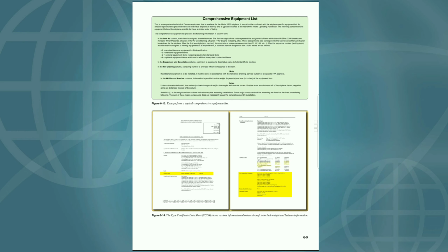VFE, flaps extended, 125 mph, 109 knots. VLO, landing gear operating, extension 150 miles per hour, 130 knots. Retract 125 miles per hour, 109 knots. VLE, landing gear extended, 150 mph, 130 knots. VMC, minimum control speed, 80 miles per hour, 69 knots. CG range, gear extended.